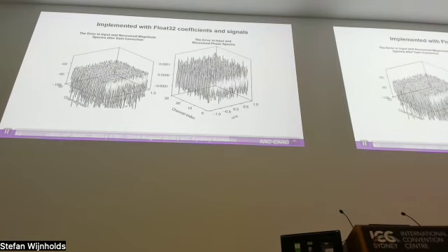This diagram shows the difference between the input and output magnitude and phase spectra, post passband ripple and propagation delay correction, where both the data and coefficients are represented with Float32 format. The results are almost identical to those of Float64 representation, indicating little to no sensitivity loss due to the reduced precision.